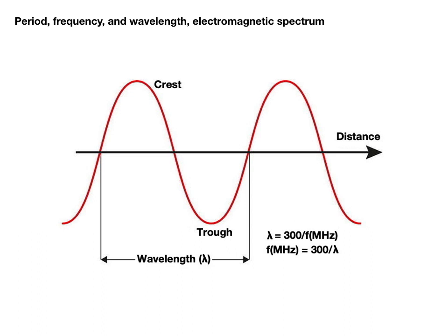As noted earlier, electromagnetic waves, including radio waves, travel at the speed of light. The distance that a radio wave travels in one cycle is called the wavelength. The relationship between frequency and wavelength is quite simple. Because all radio waves travel at the same speed, 300 million meters per second, the distance that a radio wave will travel, as measured in meters per cycle, in a single cycle, is 300 million meters per second divided by the frequency in cycles per second.